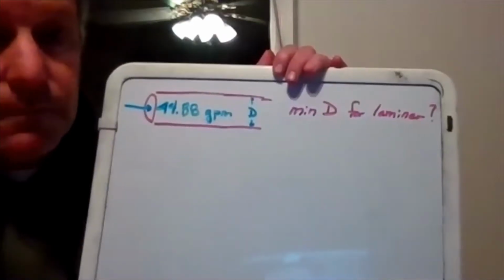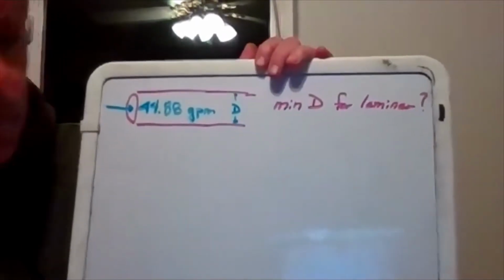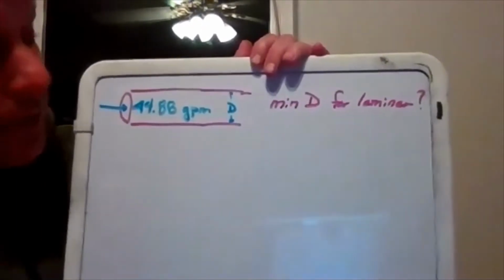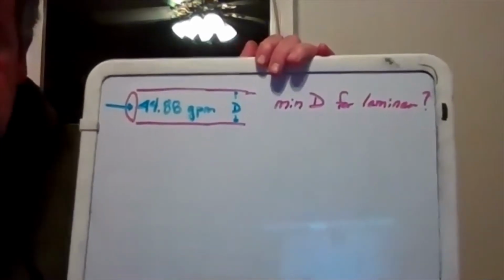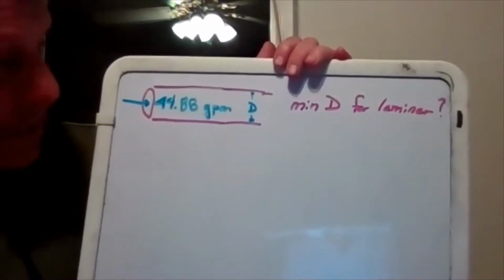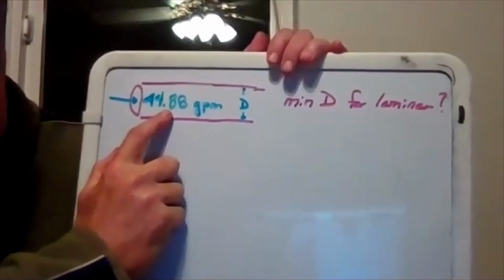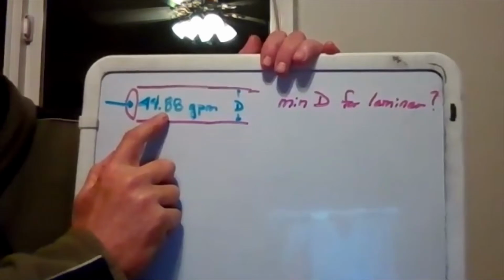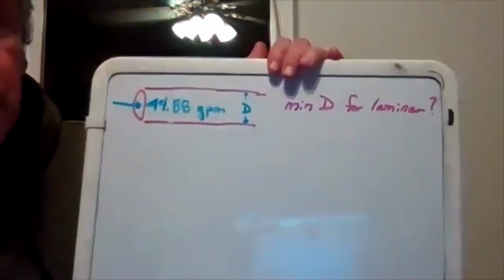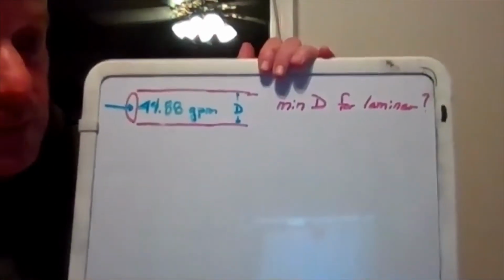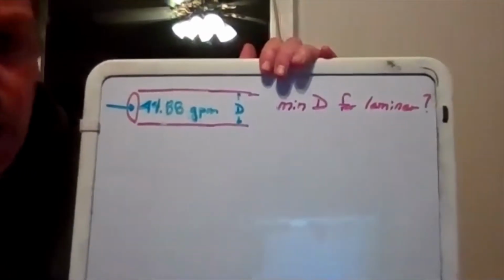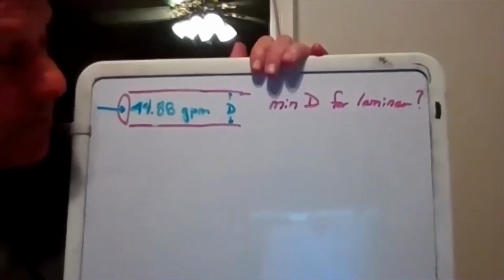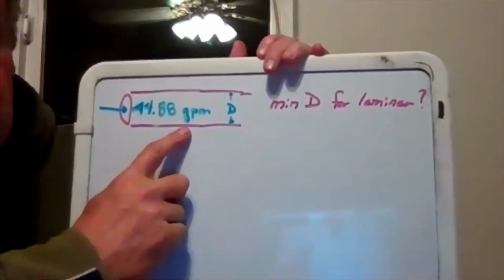So here's a good example that's a good challenge and represents something that you might do out in industry once you understand a little bit more about flow, and that's pipe sizing. I have a kind of strange number here, but you'll see why in a bit. Let's say we're trying to size pipe to carry 44.88 GPM of water. So take an example, let's say you're involved in a job where there's water for showers, and 20 showers, 20 divided by 44, it's a little over 2 GPM per shower, and you want that flow to be laminar.